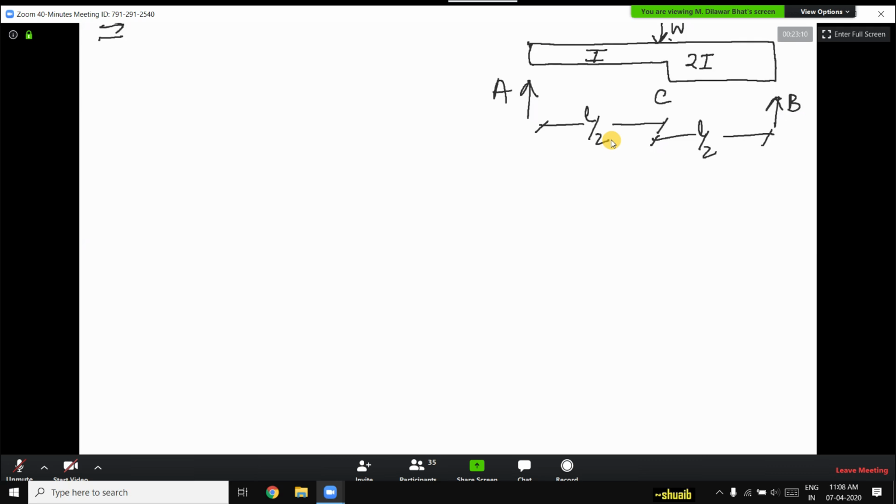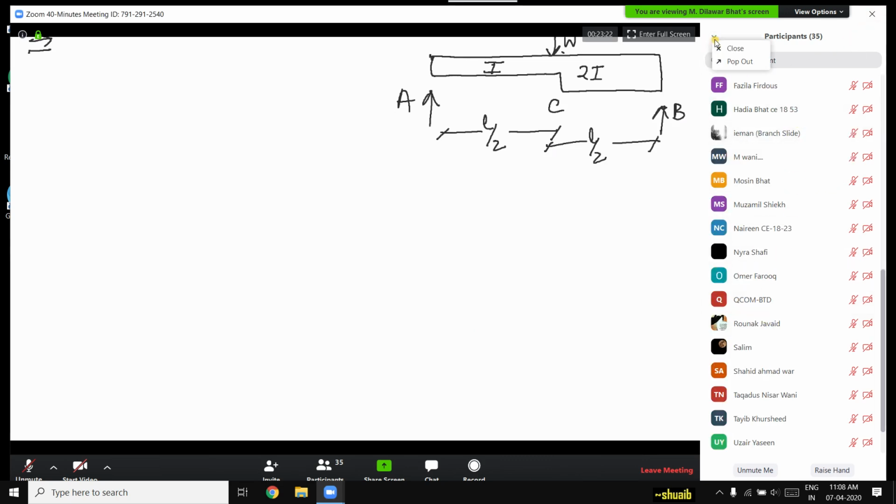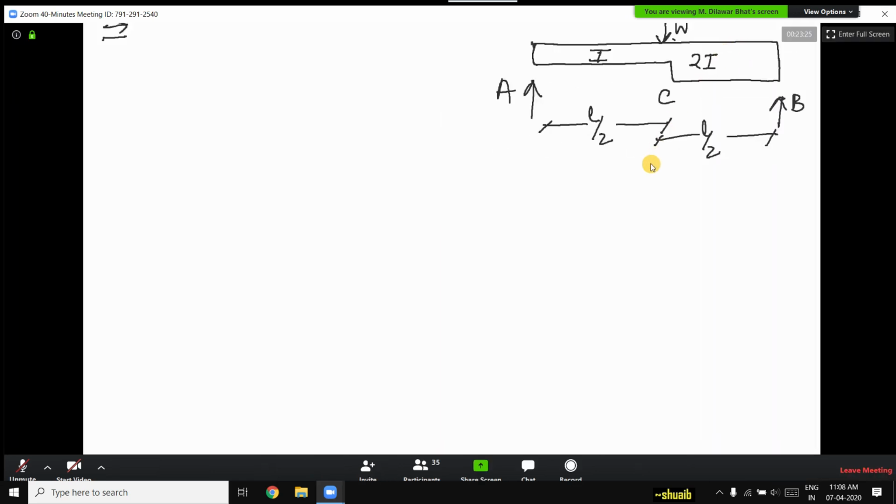Therefore from the diagram itself you can say that on part A to C, we have moment of inertia, say I1. And from part C to B, we will be having I2. That will actually depend upon the cross-sectional dimensions, B and D. On the basis of these cross-sectional dimensions, which are breadth and depth, you will be having different moments of inertia, like the way it is here.